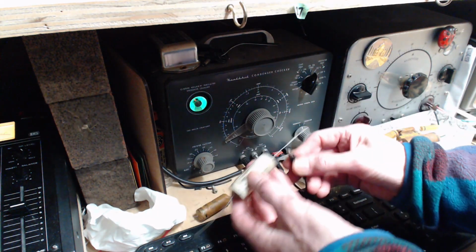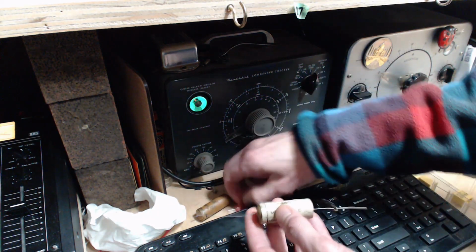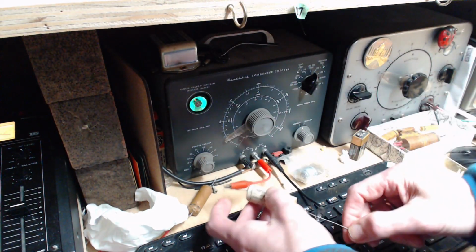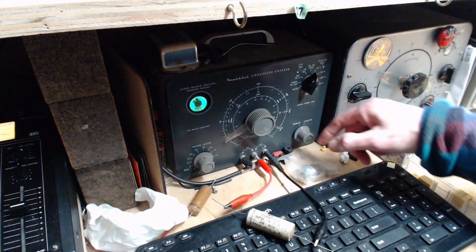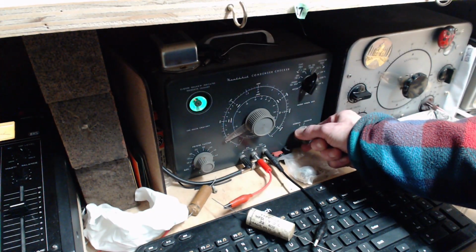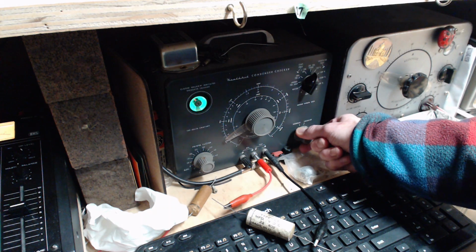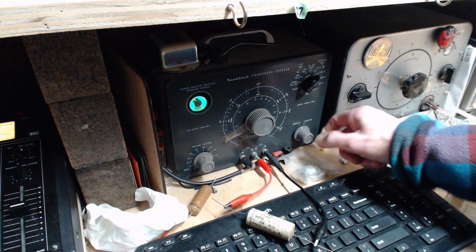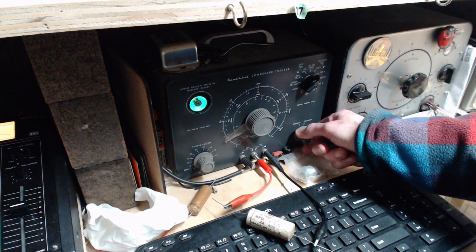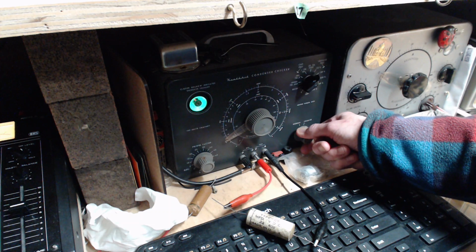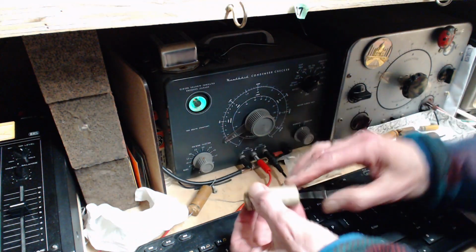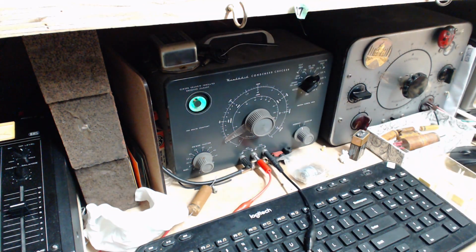Let's put the leakage test to it. Let's see what happens. This is a monster of a capacitor, though. Wow. Really well sealed. Let's see if it's good. There we go. Takes time to charge. Okay, I don't think it opened all the way. 150. No. In this position, we're trying to put a capacitor in that has no leak in it. This guy's leaky. Can't use it in this spot. It's self-defeating in a sense.